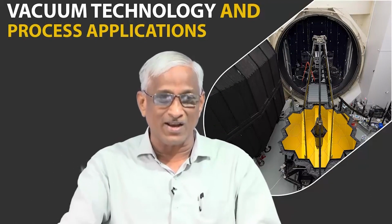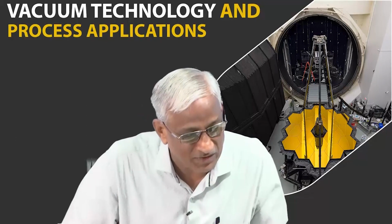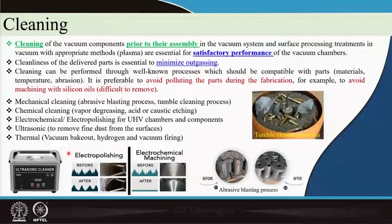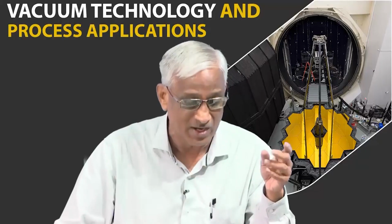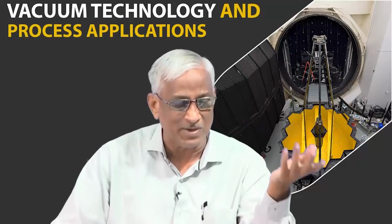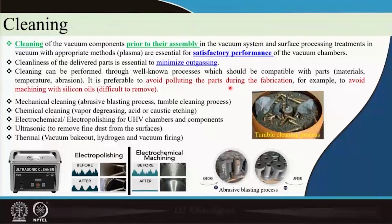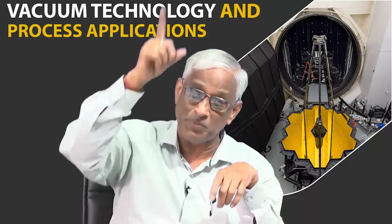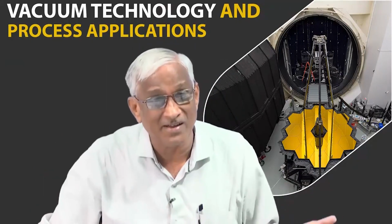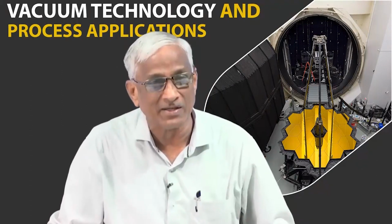And after cleaning, I am talking with respect to fabrication, not during evacuation. So, you should keep track of that. All these four are there. The most important thing is initially cleaning with soap solution, followed by deionized water and ultrasonic cleaning to remove the dirt. Later you go for ion etching or chemical etching or various other high tech things, but finally you have to remove the pollution from the surfaces. They are important for fabricating, welding, as well as in the final assembled state, when you will get less degassing. So, you have to keep track of all these things in the cleaning.